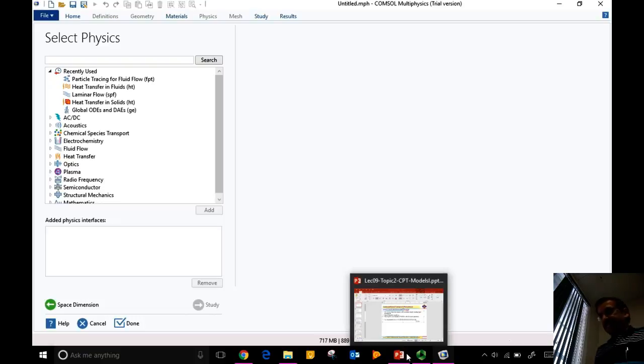I'm glad that this example came up by kind of fluke. I wasn't planning to talk about this. There is a checkbox that you will see when you're building the axisymmetric one. One is without a swirl, the other one is with a swirl. This one is without a swirl flow because there is no component in this direction. Whereas the Taylor-Couette flow is axisymmetric with a swirl flow. That means it has to write down the third momentum equation in the angular direction. In this case, it will just solve two momentum equations, R and Z. It will not solve the theta momentum equation.